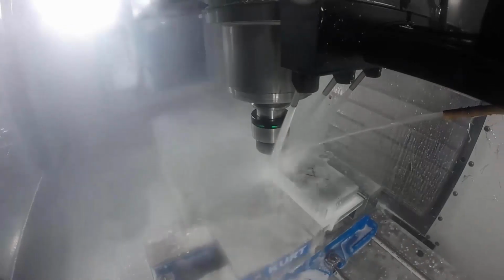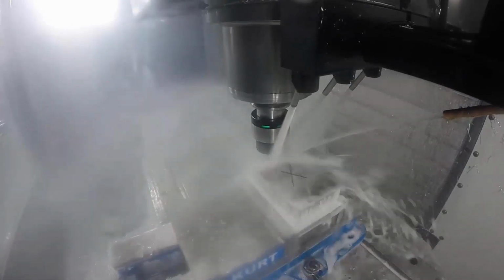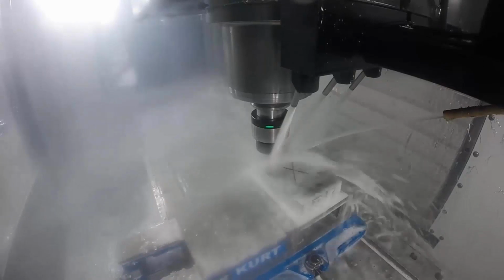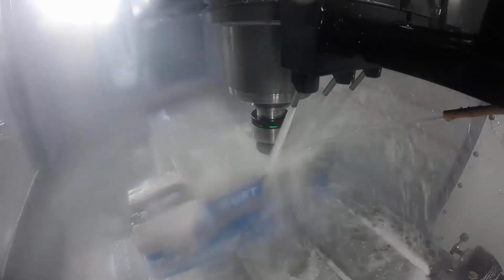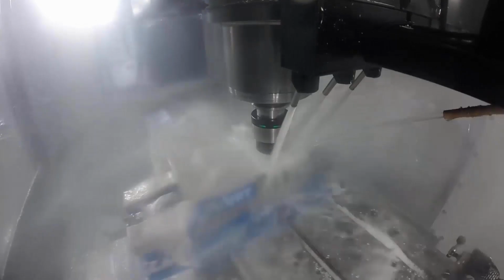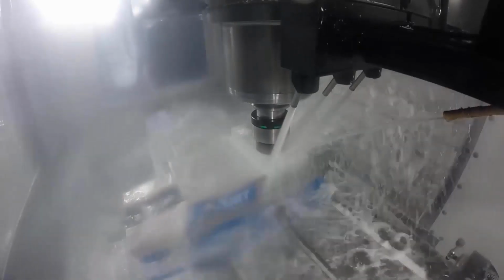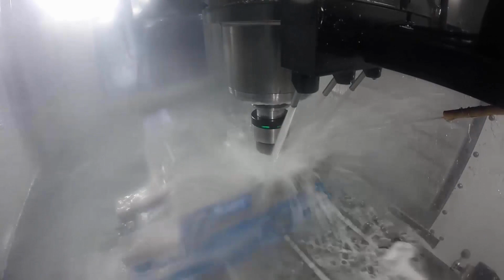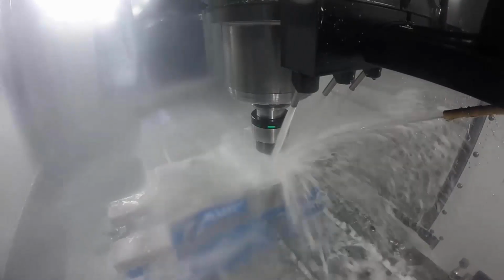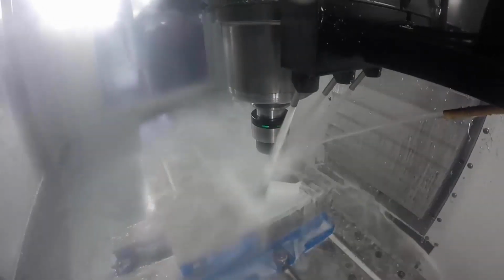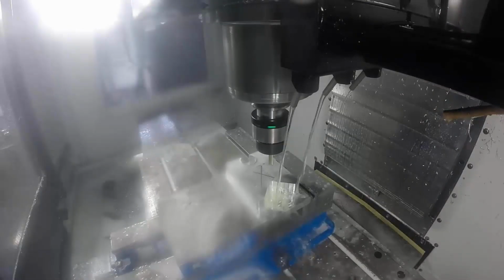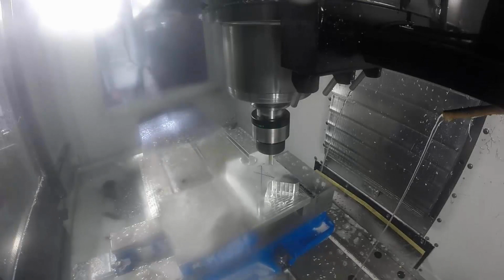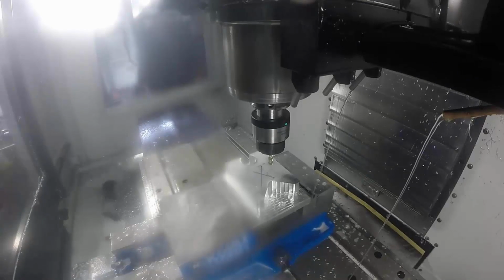This can help you complete your parts faster, giving you an overall advantage in comparison to your competitors. And because you're using constant load, this can help decrease the tool and machine wear as well. It can reduce the likelihood of tool breakage because of the strategy it takes on part entry and corner engagement. And because you're cutting with the full depth of the tool, not just the tip, this results in higher material removal rates and better machine efficiency. So you can see there, in the few seconds that I've been talking about some of the value, I've already been able to take off a large portion of material in this component using the adaptive technology.